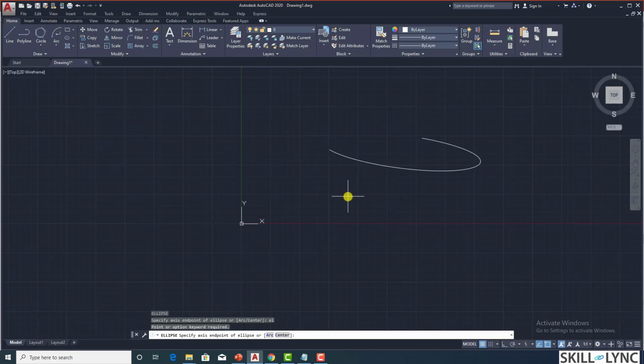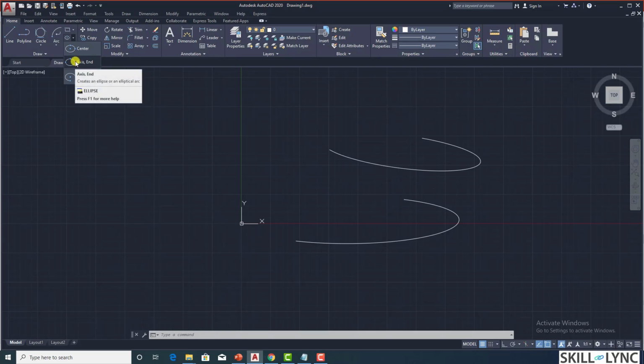Now moving forward, again selecting the arc command, we can also specify by selecting the center and the endpoint, specifying the distance, and again specifying the start point and end point. So it means that you are indirectly invoking these two commands, but by specifying the start and the end angle, you truncate the ellipse to form an arc. This is the arc command.